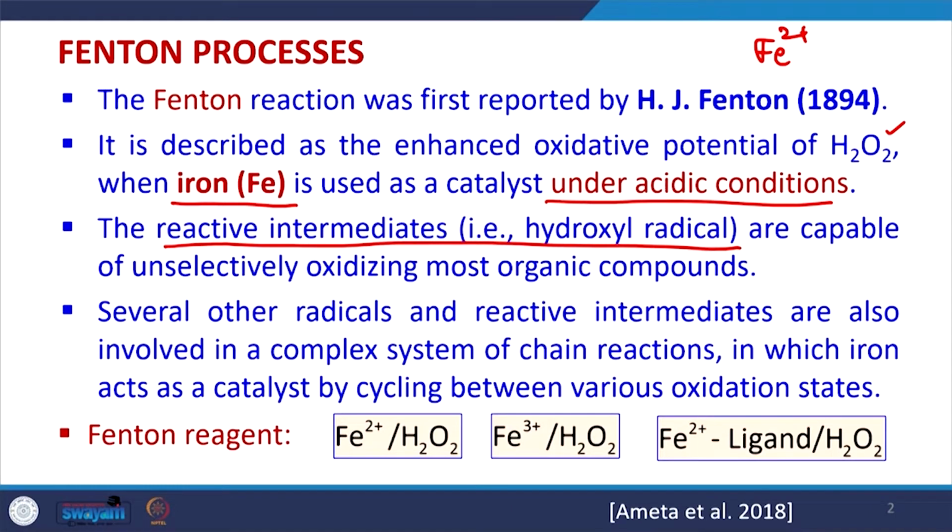Several other radicals and reactive intermediates may also get formed because of the action of Fe2+ and H2O2 under acidic condition with the different organic compounds present in the water. So, the Fenton reagents are Fe2+ with H2O2, Fe3+ with H2O2, or Fe2+ with some ligand and H2O2. This is called Fenton reagent, and it is used for the treatment of water.